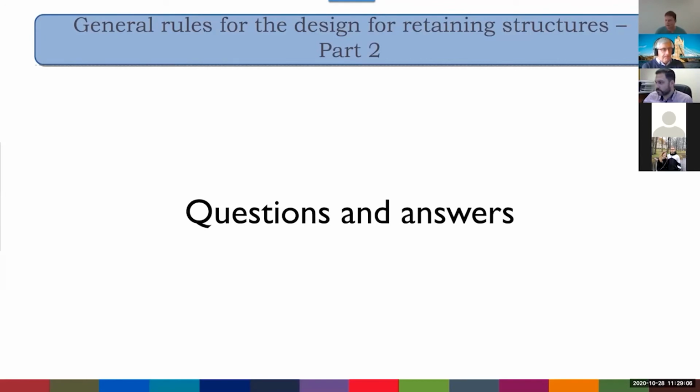Okay. For example, in UK, ideally you would do a laboratory test, and you'd either do shear box or ring shear. So that is what I would recommend, and I would take samples deliberately to do that. I would always look at my correlations because that will give me a first estimate of phi CV. For sands, the values of phi CV fall in a fairly narrow range anyway, so your test is probably only confirming a value that you can guesstimate from the simple correlations. That's why the correlations are valuable. But yes, a measured value is always better than a non-measured value. But obviously, there's an expense attached to that.